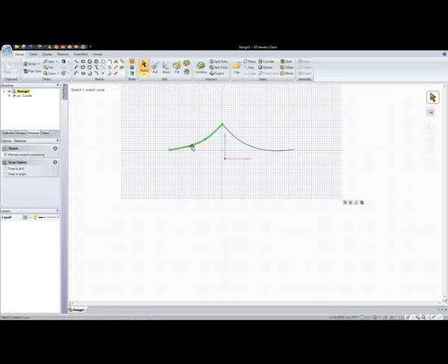Now, I'm going to left click on my line, and as you can see by left clicking on just that line, it selected just that curve. So when I select on the offset tool, it will offset just that one curve. However, if I double click on it, now I can offset both curves together at one time. As you can see now, in the offset line options on the left, the option is closed with corner. If you can see, there are 4 different curves.